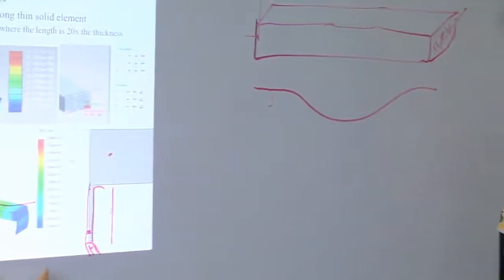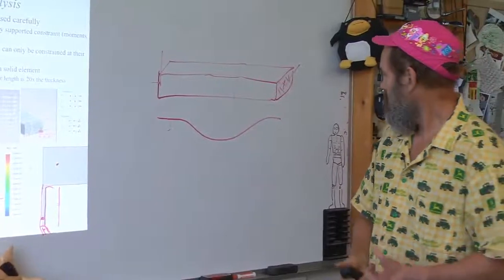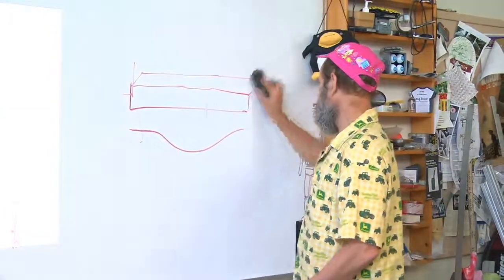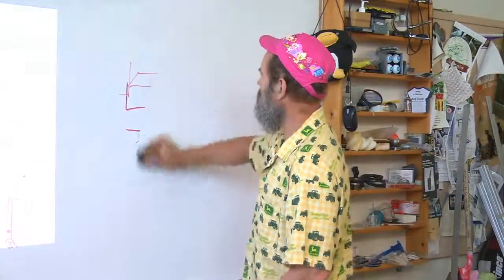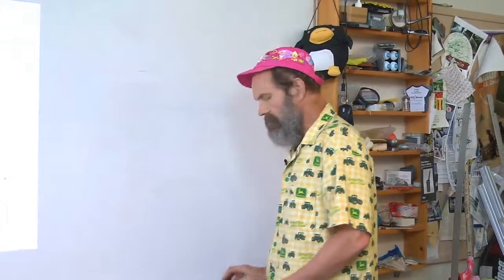This is also true for bolted joints. And we will be talking about this a lot more in the next topic, topic 9 on joints. There's a way you can model bolted joints very, very effectively in your solid model such that when you do the meshing for finite elements, you get a very accurate prediction of the stiffness of a bolted joint.